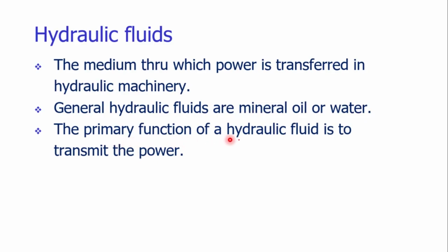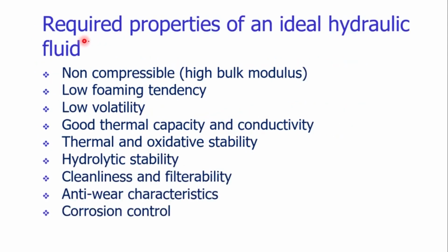The primary function of the hydraulic fluid is to transmit the power. We have to transmit the power from the pump to the designated load or the desired application. There are certain properties that an ideal hydraulic fluid should have. The fundamental property is that it should be non-compressible. It should not compress, so that it will transmit the power efficiently. It should not form any foam during the operation. It must be less volatile.